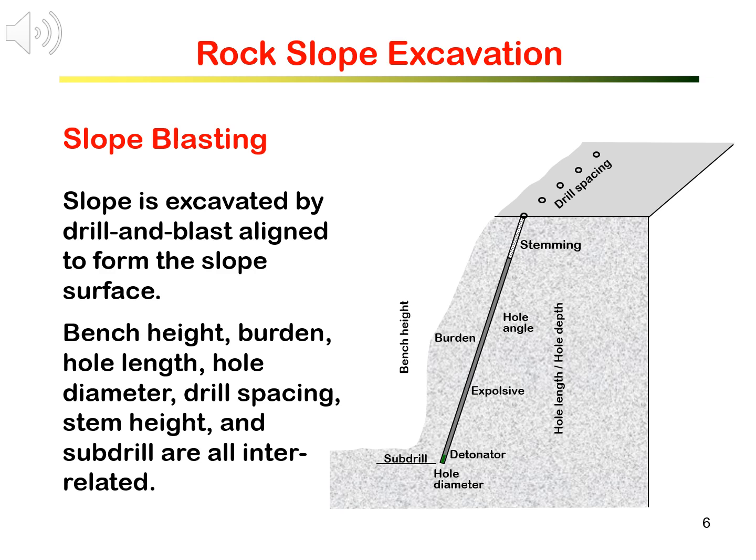To design the blast, we need to consider the bench height or the slope height, the burden of the rock to be blasted away, the hole length which should go beyond the slope toe to include subdrill, the hole diameter which also governs the amount of explosives when it is filled with explosives, the spacing between drill holes, and the amount of stemming materials covering the explosives in the hole as stem height.